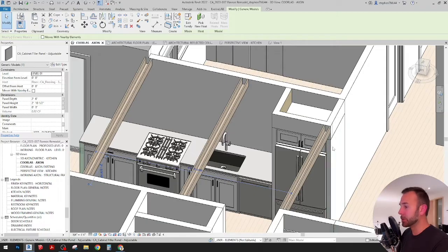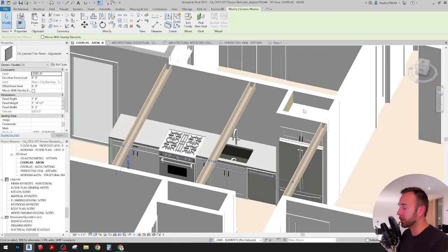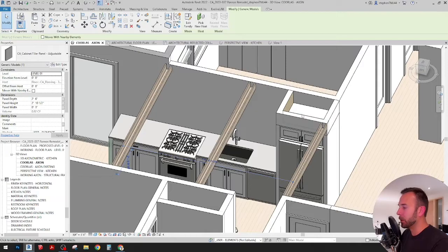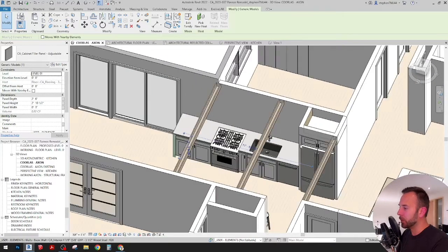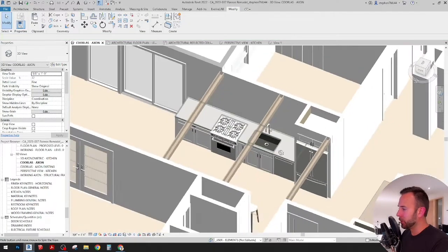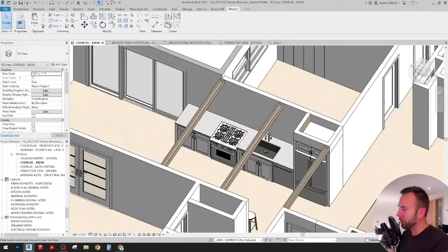If you have the space, you can shift things down a little bit so that this beam is bypassing it, and then you can get a 2 foot tall cabinet going up to the bottom side of the ceiling, which is what I would prefer. And then you can bring out this load bearing wall a little further, save some costs on the beam. So that's what I will do when I propose this to the client. But like I said, for our purposes, we'll just keep moving forward here.